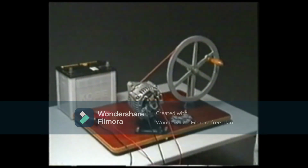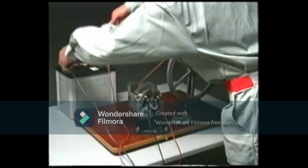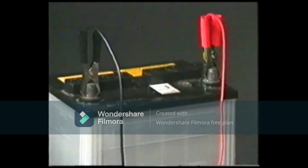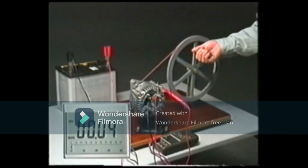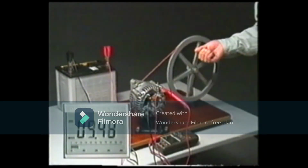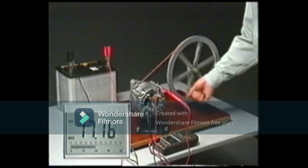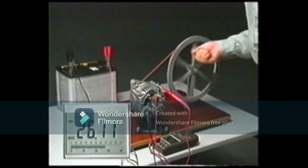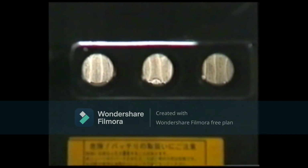Now we will explain how the voltage regulator works. First, battery voltage is applied to the rotor coil of the alternator. Then the alternator rotation speed is gradually increased. Let's measure the voltage generated at terminal B, which is the alternator output terminal. As you can see, the voltage increases steadily. If this continues, the electrical components will be damaged and the battery will be overcharged.